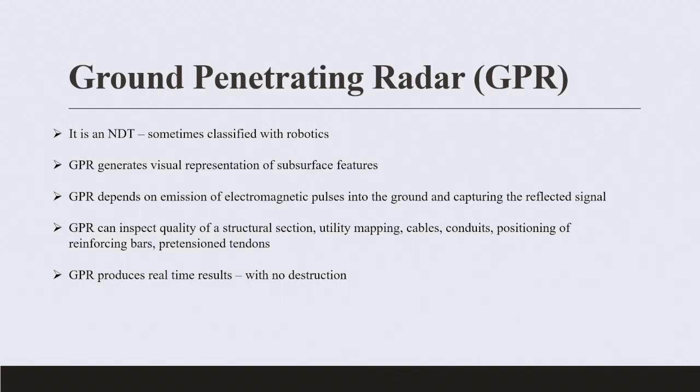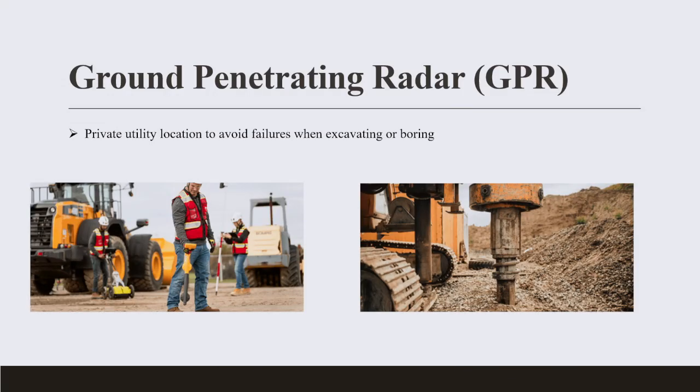GPRs, or ground penetrating radars, we talked enough about them. It is an electromagnetic pulse, and you measure the reflection, and you have to be very well trained. It took me a while until I learned first how to pick the right GPR system, what frequency for what depth and what accuracy. That's one thing. And then how to interpret the outcome. Are you seeing a void? Are you seeing a rebar? Are you seeing different soil strata? You have to learn how to read this. It's like a cardiograph. If you show it to somebody who's not a medical doctor, he will just see lines, but he cannot interpret this.